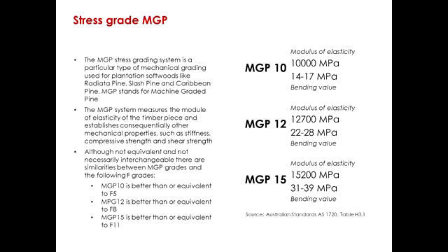The important thing you need to know is that in this case we're actually measuring all the properties of the timber product, in particular the modulus of elasticity. So this is a much better process when you need to make sure that you're using your product for structural applications, so that you will know exactly how it will perform.